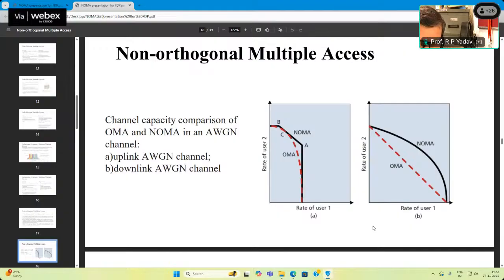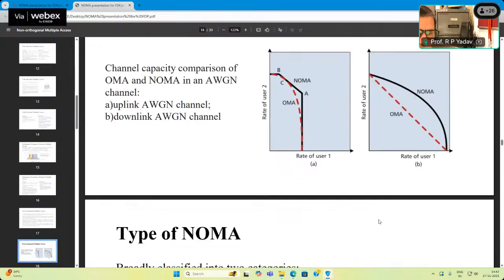If you plot CDF on the y-axis against the throughput for OMA and NOMA for 2 or 3 users, the users' download speed can go up to almost 7-8 GB in comparison to almost 3 to 4 GB in the case of orthogonal systems. So this graph shows that NOMA is a more efficient, more useful technology to increase the speed of the system.